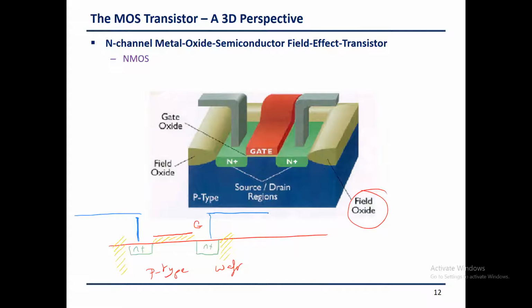Okay, but the wafer is built from pure silicon atoms, right? The wafer is built from pure silicon atoms. Typically, it is P-type, so it is processed a little bit. Here, the wafer is thick, right? The wafer is very thick. And really, they work on the surface of the wafer. So they make sure that it is uniform and it is P-type material, okay? And then they start to implant in it the transistors. So this is silicon. Then they treat the surface and then they start to build the transistors.